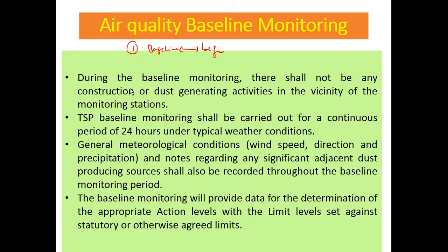Okay, so 24-hour baseline and monitoring are similar. General meteorological conditions, wind speed, direction, precipitation, and notes regarding significant dust production sources should also be recorded during the baseline monitoring period. So baseline monitoring will provide data for the determination of the appropriate action level and limit level, set against the status of the agreed limit. So baseline is important as the agreed limit or compliance limit that the contractor or main contractor needs to follow.